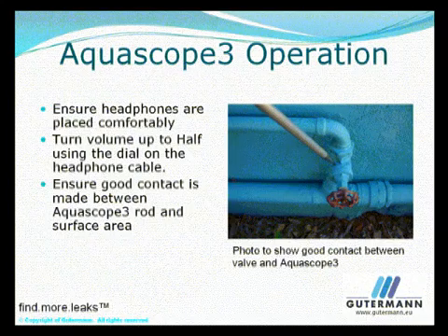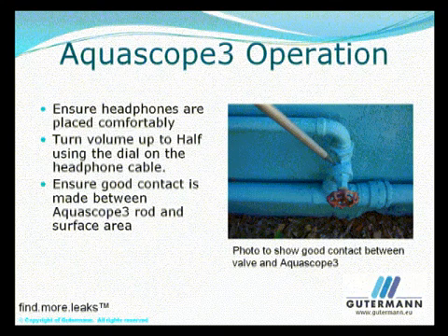Using the volume plus and minus buttons on the front of the control unit, set the volume level at about 70%. The level is shown on the display. Adjust the volume setting on the headphones to about 50%. Push the end of the listening stick against the water pipe in your house or office. Hold yourself and the microphone still.